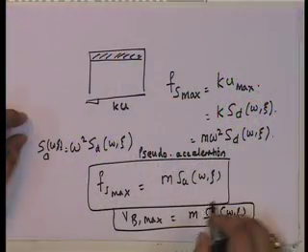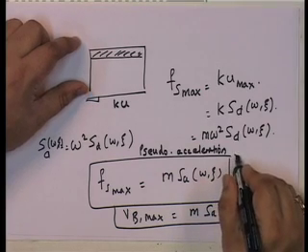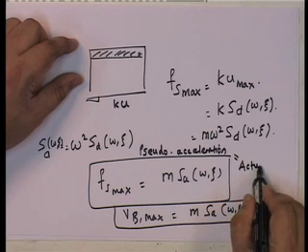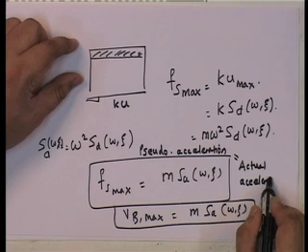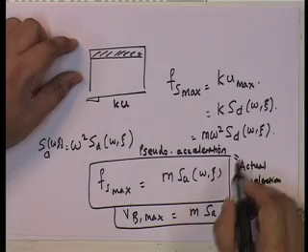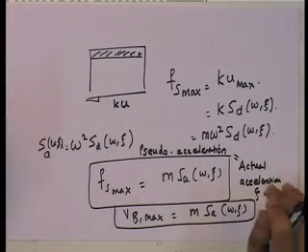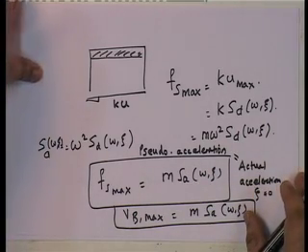Okay. So, in a way, the pseudo acceleration is equal to the actual acceleration, total acceleration, if psi equal to 0. Only for psi equal to 0 is the pseudo acceleration equal to actual, otherwise it is not. However, the pseudo acceleration spectrum is actually more important to us, because what does it do?